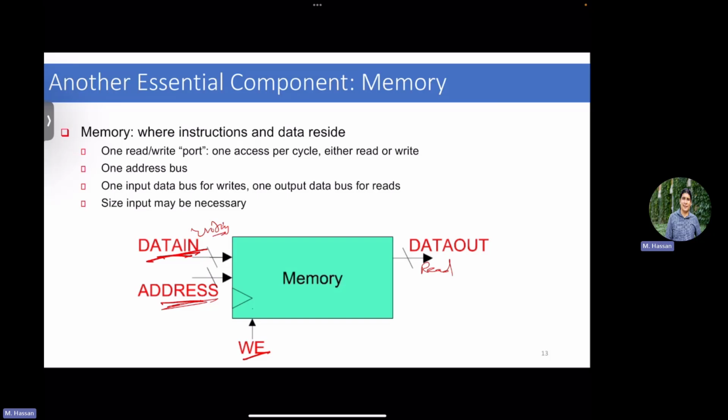And if we want to go to a memory, we are using a register to address the memory, whether it's data or an instruction. In case of an instruction, what register are we using to access that memory? What is the name of the register that holds the address to go to the instruction? Yeah, the program counter. Thank you. And if it's a data memory, remember our load and store instructions are written in something like this. We had that example last time. We read that register, add the offset, and then use it as an address. So you still take your address from a register.